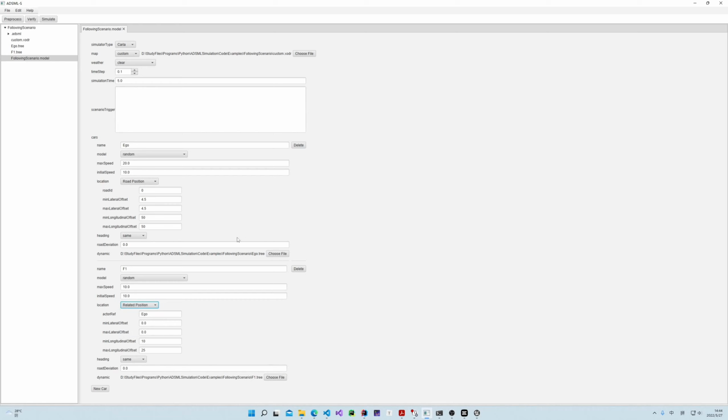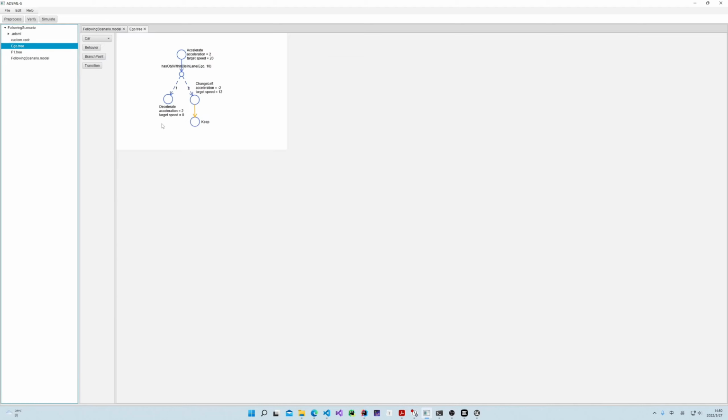We can bind a behavior model to the corresponding vehicle. The behavior model is comprised of a sequence of behaviors and triggers organized in a tree-like structure, which describes the dynamic process of a vehicle in the scenario. Inspired by the theory of state transition, we represent behavior as a state node, with directed edges connecting nodes and the trigger serving as the conditions. Here we only allow the state transition to be fired from parent to child nodes, starting from the root.